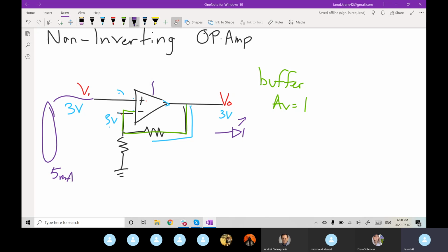Well, because the output is powered by the supply rail of the op amp, we are able to source the power from the op amp, which, if you go through the data sheets, you'll find its voltage and current ratings, and maybe this op amp is able to source 100 milliamps.